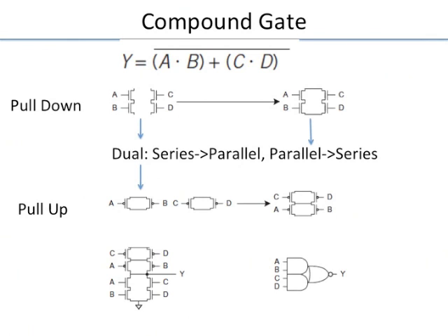So this is how we design CMOS gates. You have the truth table. From the truth table, you figure out the Boolean equation for y equal to something. A CMOS gate is always inverting, right? You always have a bar on top, because when inputs are all high and the pull down is activated, the output goes to 0. So it's an inverting gate.